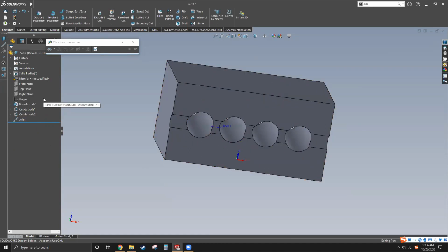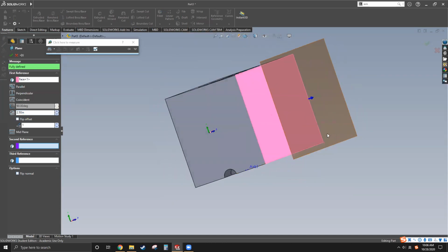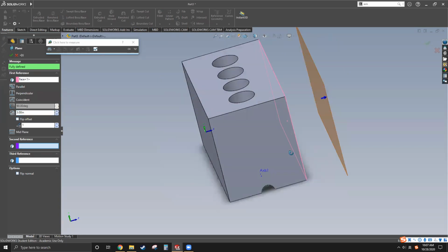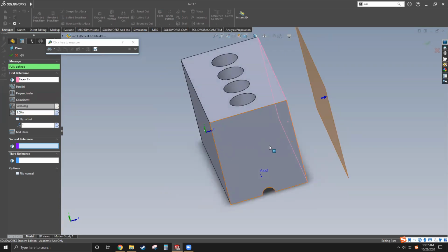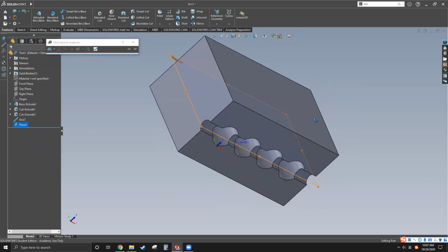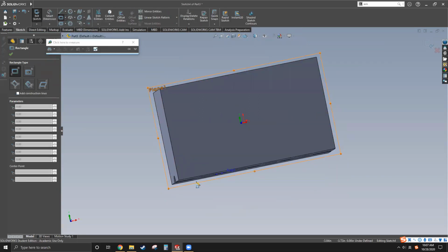All right, so the meet plane. Let's click the plane and select a surface that you want to be offsetting with, and offset it. This is set to 3 because we know the thickness of the block is 6 inches, right? 6 divided by 2 is 3 inches. And 3 inches, we want to go towards the model, not outside of the model. That's why we're going to flip offset, and here's the plane. So this is the meet plane we just made right in the center. And we're going to sketch the rectangles right on that plane.